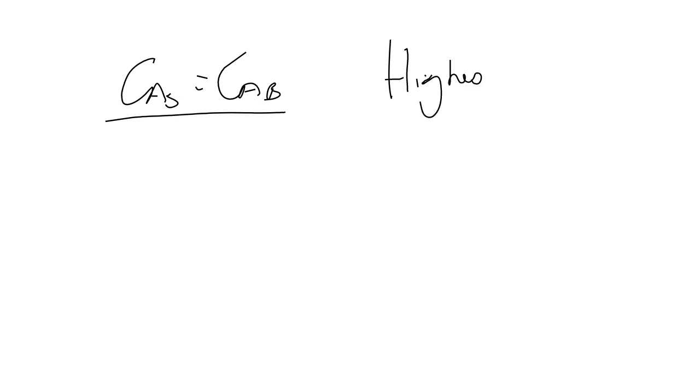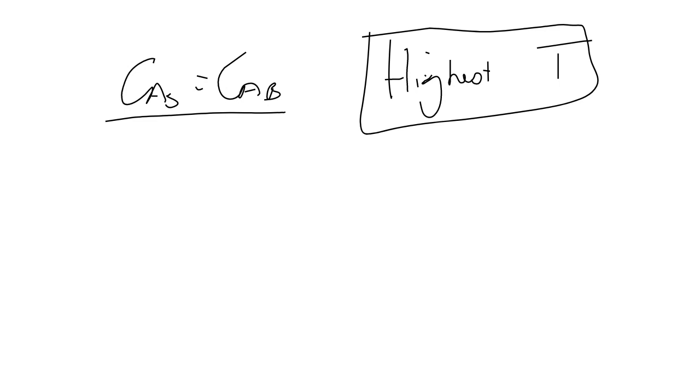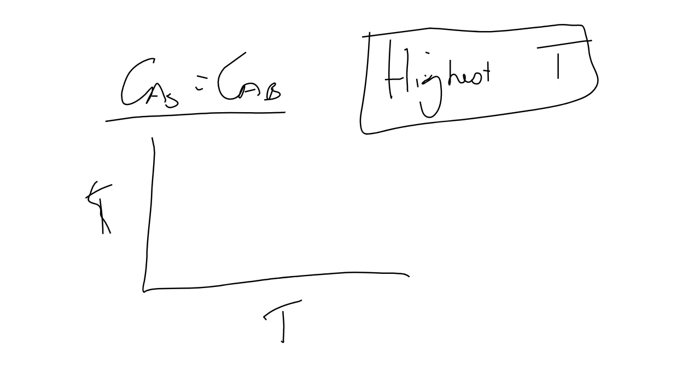You also need to make sure that the researcher proved that Ca surface is equal to Ca bulk, therefore that external diffusion didn't play a role at the highest temperature where he performed his experiments. Because if you look at the temperature profile, it's easy to have, at low temperatures, a regime where you are free of external mass transfer, and where this applies.